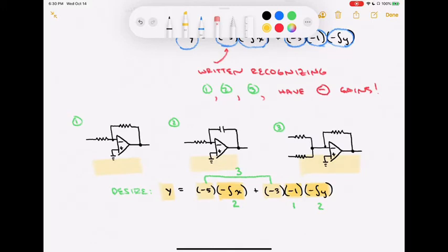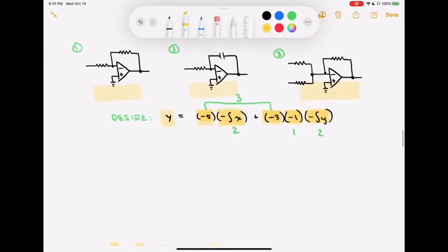I could do that with that scale factor, so circuit number 1. And then the last piece, when I'm going to sum these 2 pieces together, I'm going to hook those 2 together, so that's why the line goes between them, and I'm going to use that summing circuit to bring these 2 pieces together, each with gain. Now, I recognize that there are different ways of realizing this. You could put that gain associated with other parts. I could have done the integrators with the gain. I think it's informative to look at how to do gains when you're summing in, because there are some simple rules there that help you when you're doing that summing operation plus wanting to get the gain.